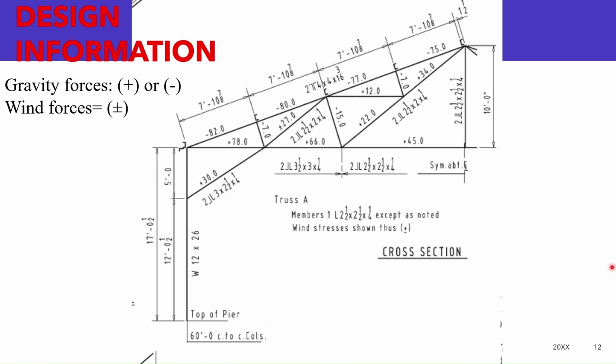the cross section is taken through the 60 feet width of the structure and shows the sizes of columns, knee braces, and truss components. These are the knee braces and sizes are also given for them. For knee braces it is 2 angle sections 3 by 2.5 by 1/4.